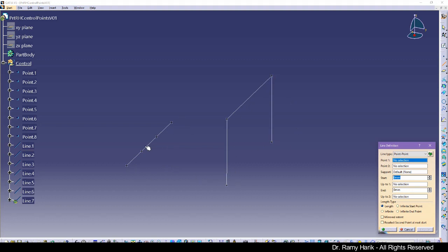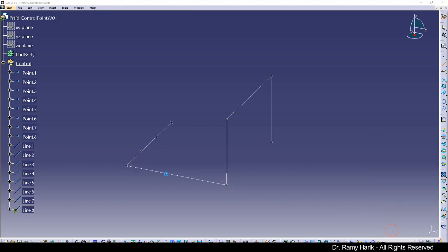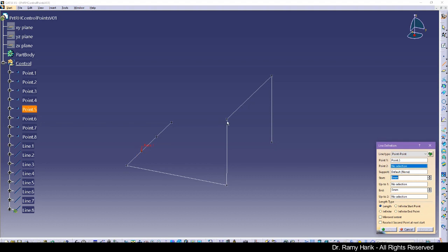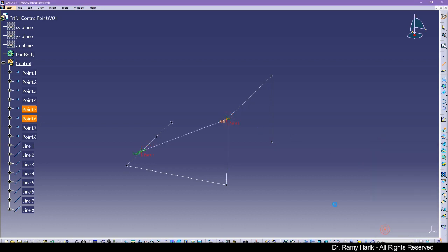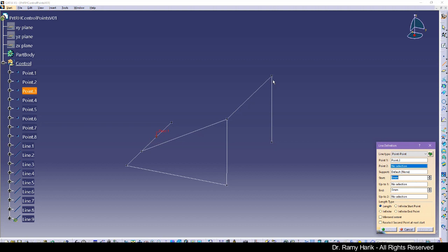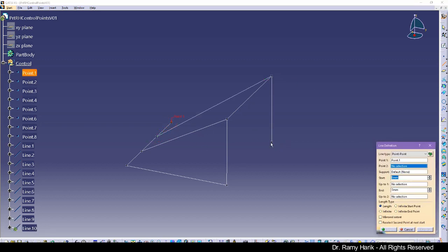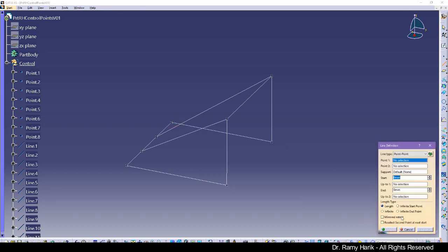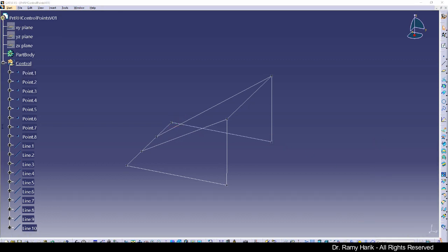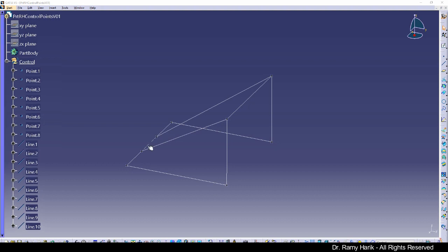What I'm going to do is create my lines along the V parameter. So this is my second one. This tutorial is really excellent in the sense that it demonstrates to you how to create complex surfaces. And we are going to see that in brief seconds. So we have created the different contouring lines and the contouring parallels. Let's go ahead and color all of our U parameter, and you're going to see what I mean, in green and the V ones in red.